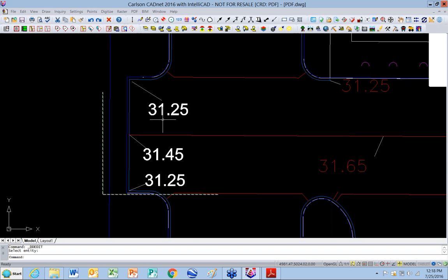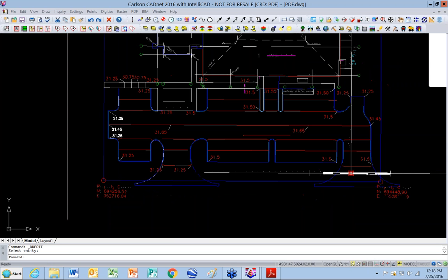If later on I wanted to elevate, I would use the civil module, and there's a 2D to 3D polyline in there that allows me to elevate it into 3D. That'll be in a different webinar. But on this one, I'm just showing you how to take a PDF file in and convert the polyline text into actual text to use in CAD.